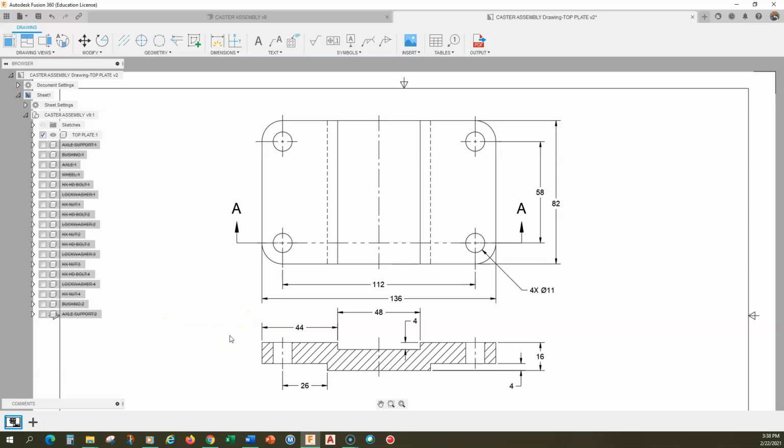All right. From a functional point of view, I think it is clear, since this middle gap is not really functional, but the foot pad here is, the 44 is more appropriate than the 48. Okay, so we'll put the 44 on there, and we don't need to put a 44 over here because of the same reason why we have 126 here and not one over there on the right-hand side. And then the last thing we need to do is the radii on the outside.